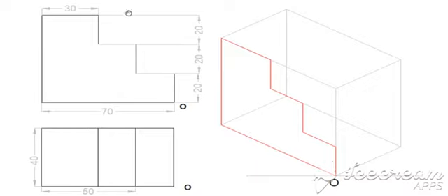So let's first draw the front view on this front view side. You can see that this height is 60. So draw 60 mm here. Then again 30 mm, this same 30 mm. Then along the height towards the downward direction 20 mm. Then here you can see that this is 70 mm. So draw the 70 mm line. Again height-wise 20 mm.